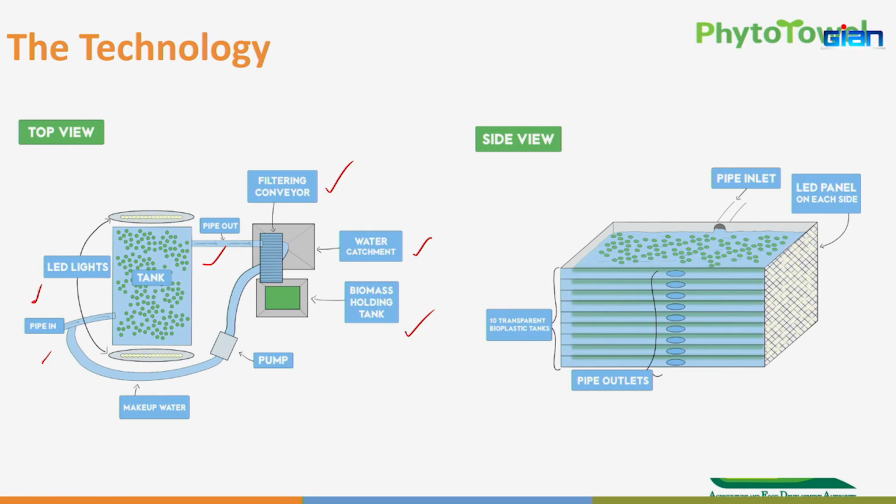And if you want to make it even more automated, you put a sensor here to measure its BOD and COD, and then again your machine learning, that means you fit in an equation to say that when BOD is less than 50, it should be discharged. Otherwise, it continues within the same circle. Yeah. So, a simple idea from a beaker, of how you can grow duckweed. You can make as complicated a design as you want.